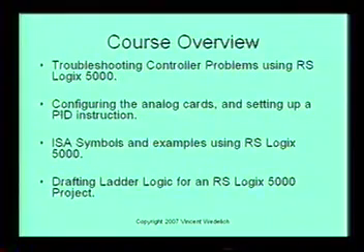On the ISA symbols, process engineers actually explain what they want you to build by showing it in ISA symbols. So they do piping and instrumentation diagrams. You sometimes say it's a PID, P and ID. It's not a PID, proportional integral derivative control instruction or control scheme, although it could be. But what they're doing is they're doing flow diagrams. They're showing you the flow and they're giving you these ISA symbols.